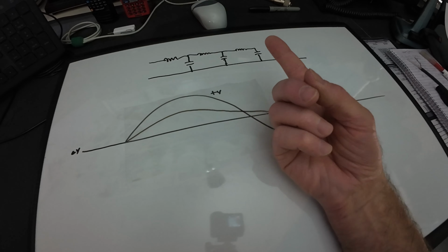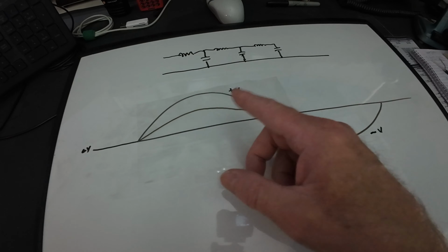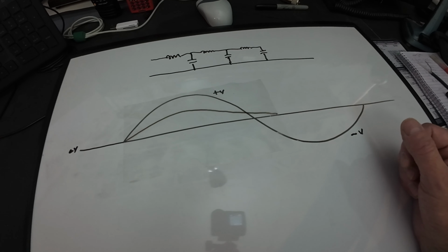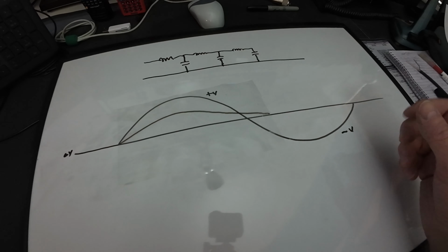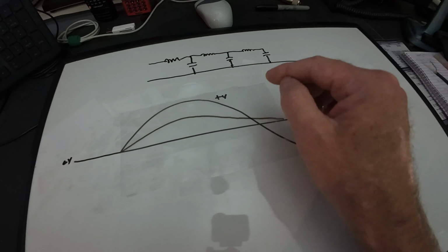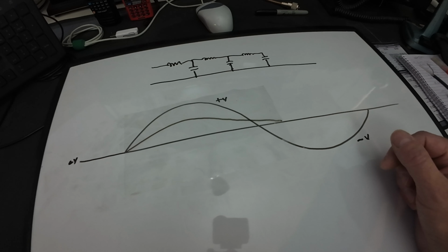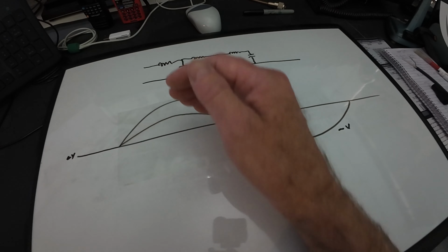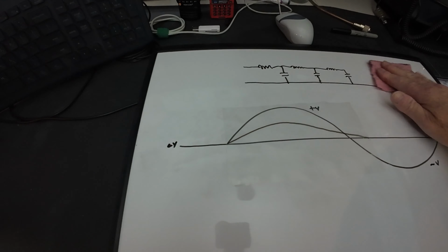That is in there because all of the leads inside that meter are adding series inductance, and we have to counter it with some capacitance. So there'll be a little disc capacitor shunted to ground right at the SO239, or the output of that device. What we're trying to do is get that back in phase so that our voltage and current waveforms are in phase once more.